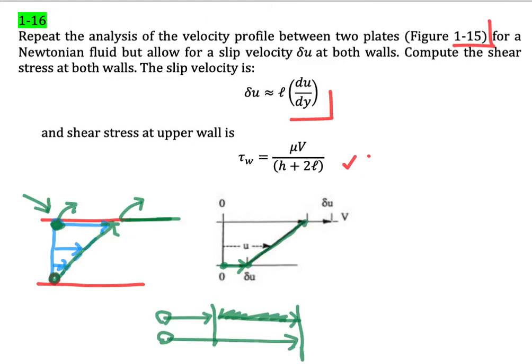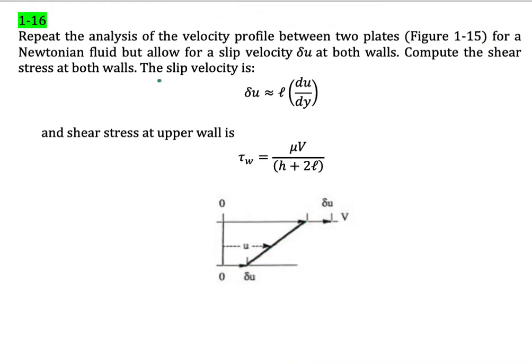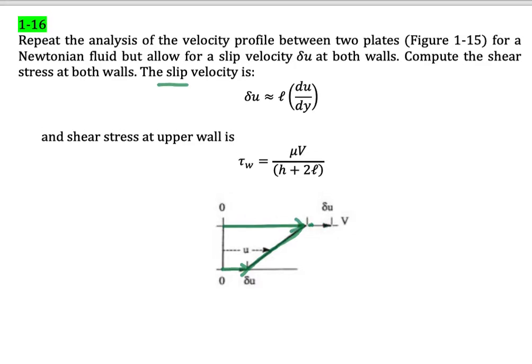It will move, but it slips a little bit. So it will move at slower velocity. That's why when you draw a velocity profile for slip condition, it will become like that. It means you need to add an extra velocity at the bottom here, but at the moving plate, the velocity is reduced, because this is the slip velocity. So I hope you could imagine. Okay.